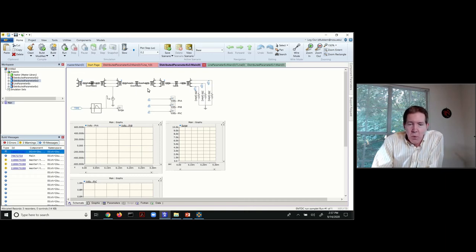And then when you get to the cable, I don't think you necessarily need to split this out. I just did this to give me a little more flexibility in the model. And then at the load end, I split it up as well, so you can see that we have a Y-connected load. Sometimes I just split things up so you can see what's going on and there's no ambiguity in how this is being interpreted by PSCAD.